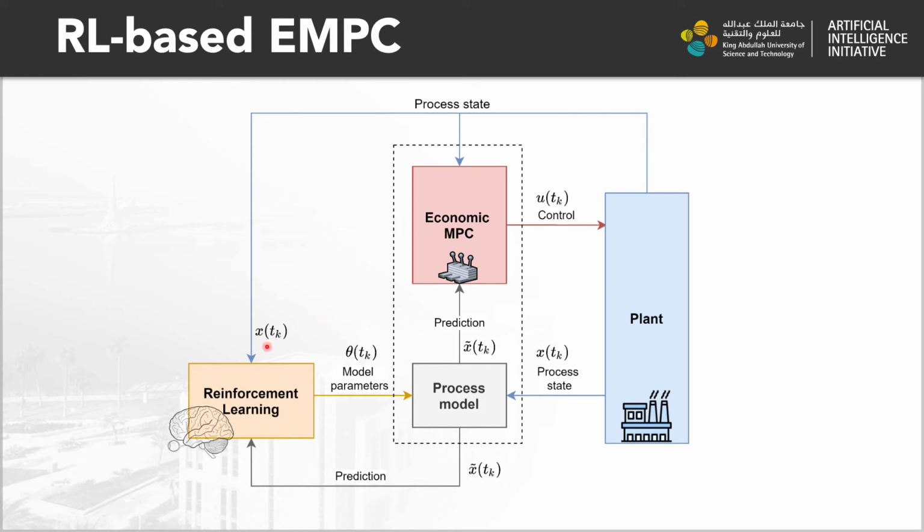The reinforcement learning agent compares the measured states with the predicted states and modifies the model parameters accordingly. The main objective of the reinforcement learning agent in this framework is to learn a policy that responds to plant model mismatch caused by the continuously changing system parameters. This framework allows control, optimization, and model corrections to be performed online and continuously, making autonomous reactor operation more attainable.